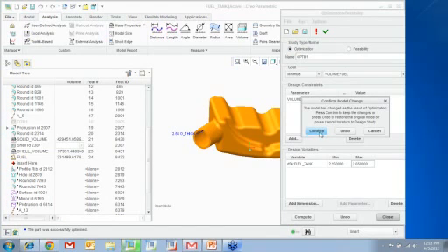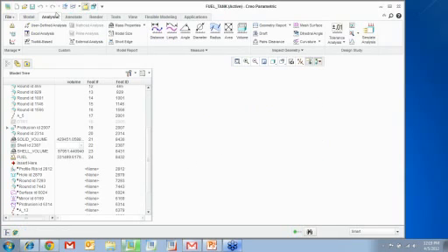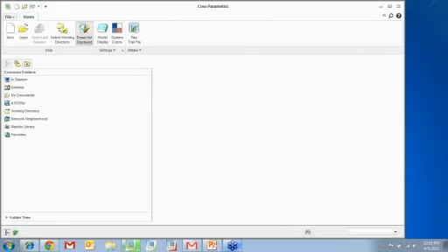So if I close it and confirm, notice it tells me that's pretty much what my volume is. Now you see that you can increase the accuracy level of your part and you can get to more zeros, or get closer. You can increase the percentage of convergence of your optimization to avoid any kind of errors like these. You can say, I want a percentage of convergence of 1%. So allowable error is 1%. So it's going to get much closer to 330,000 exact. So anyways, that was volume analysis.